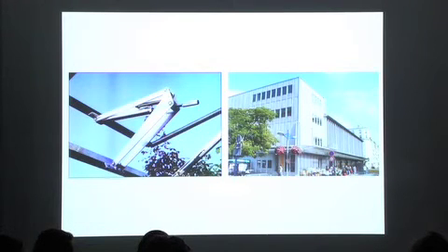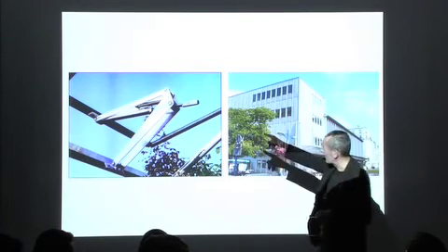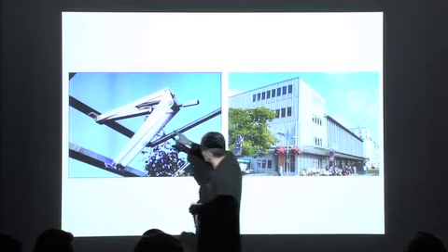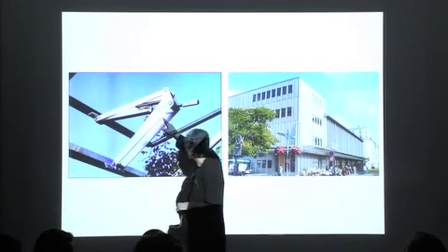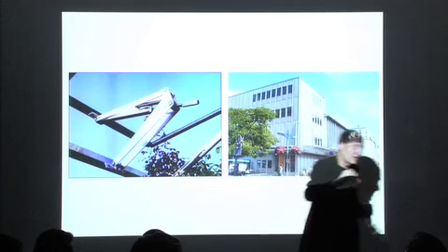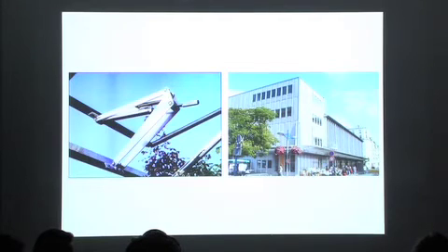There are some quite old-fashioned control devices. Wax-actuated ventilation, which has been used since Victorian times in greenhouses. I don't think that's actually a wax. It might be. I think in this tube you have wax. So when it gets too hot, the wax melts, the tube opens up, the window opens, you get air into the greenhouse. Immediate response mechanism. That's been around for a long, long time.